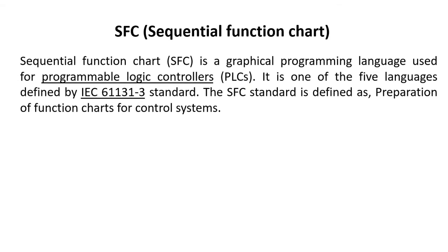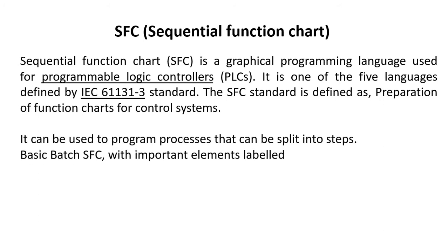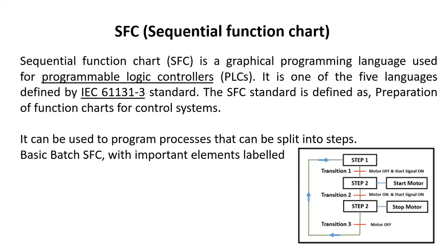What is SFC? SFC is nothing but Sequential Function Chart. It's a graphical programming language for PLCs. It is one among the 5 languages defined by the IEC 61131-3 standard. The SFC standard is defined as preparation of function chart for control systems. It can be used to program a process that can be split into steps.